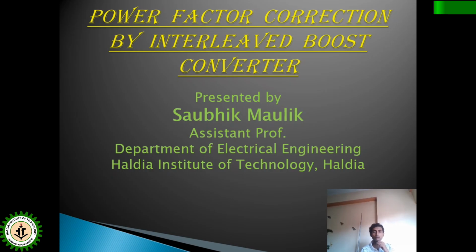So that is why, after rectification from AC to DC, we use one converter, a DC to DC converter, and the current drawn by that converter is controlled to make the input current the same as the input voltage, having the same sinusoidal shape. Now among different DC to DC converters, the boost converter draws continuous current. That is why the boost converter is most suited for the purpose of power factor correction. Also we'll discuss the interleaved boost converter in this video.